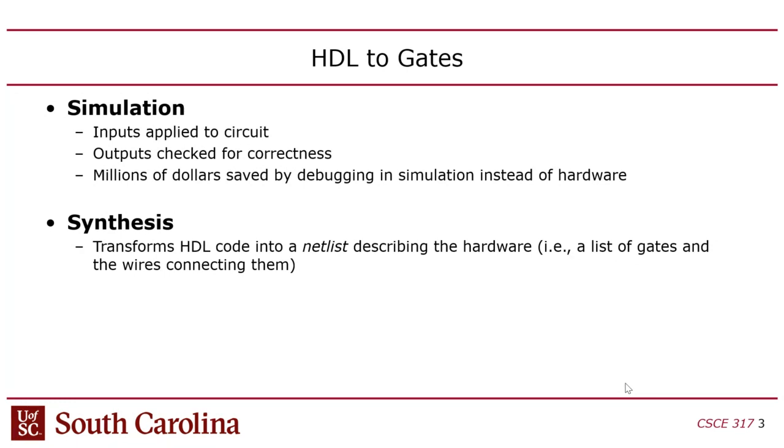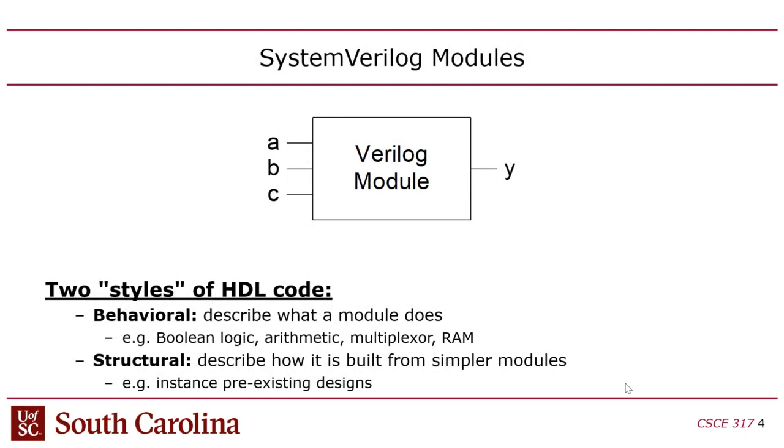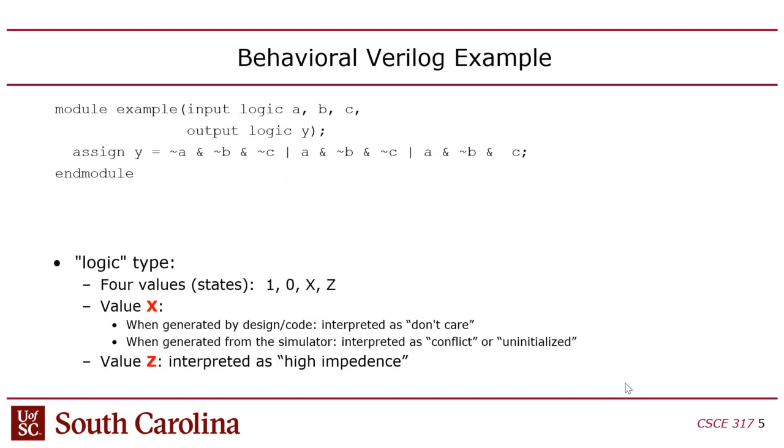So I mentioned in the quiz there's simulation and synthesis. There's behavioral and structural modules. You have modules. Modules are structural elements because they're intended to be connected together in a structure. So modules have inputs and outputs, and when you instance them, you connect them. They're kind of like having classes and objects. You instance a class as an object.